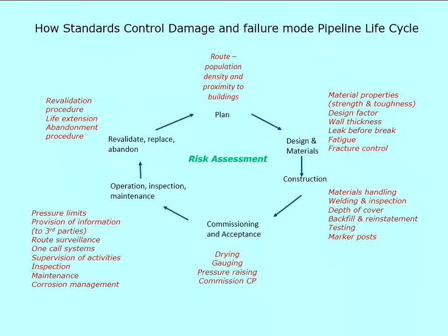And the other thing here is you're going to study risk assessment in some detail. In fact, you may have already started it. The codes that apply, the ASME code and the UK codes that are based on the ASME code, are integrity-based codes. They're not risk-based codes. Okay. What that means is you can't just ignore the rules in the code and do a risk assessment and say it's okay. You can't do that. You've got to apply the code.